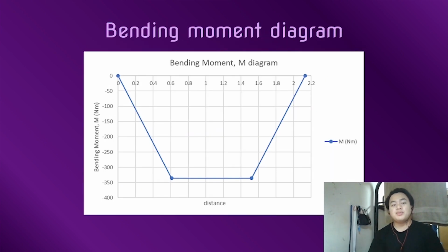So let's move on to the bending moment. As you can see, there are only 4 points, but there are 6 points there. M2, M3, M5 and M4 are distinguished as 4 different dots, because the distance between M3 and M2, and M4 and M5, of those two is so small that in the graph plotting it is near to becoming a singular dot, but we must distinguish them as 2.